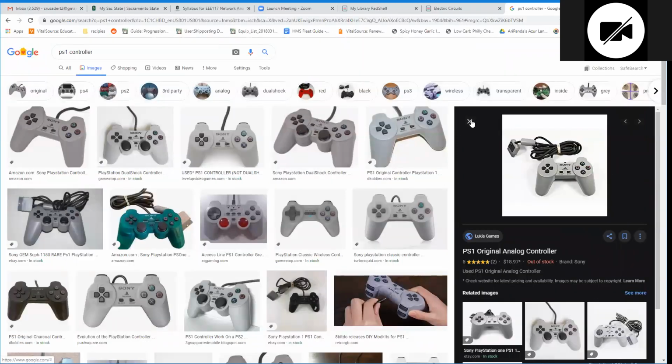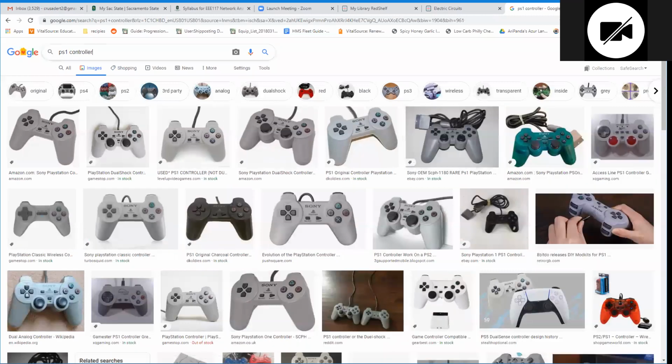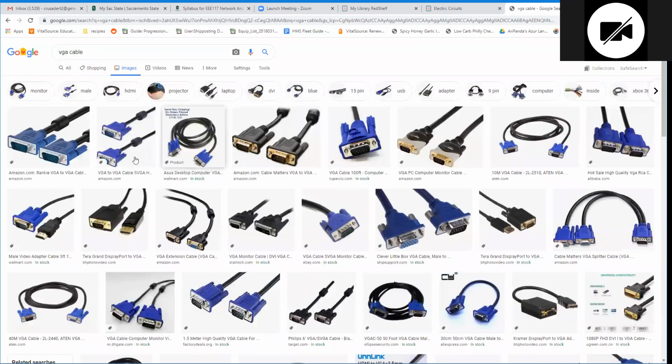What it is, it's a filter, right? You could actually take this off, by the way, and throw it in the garbage if you want to, but it filters out unwanted noise. So sometimes the older controllers, because the cable is long, and if you put it near other sensitive electronics, like a microwave or your old school cordless phone, it would mess up the signal. It really would. So you have to put a filter to filter out the high frequency noise, so the normal signal that it wants will go through. That's right, VGA cables have that, right?